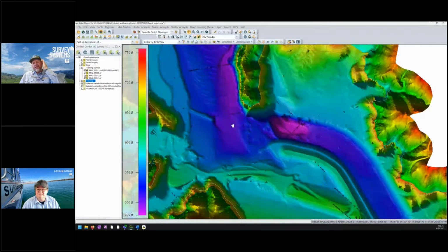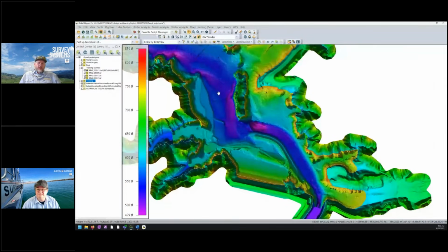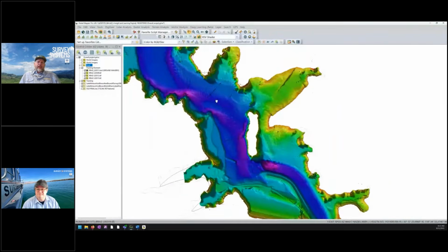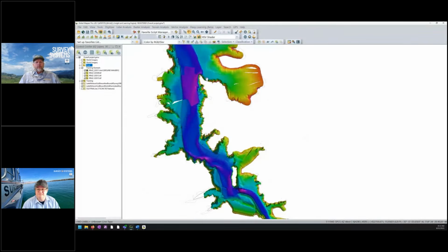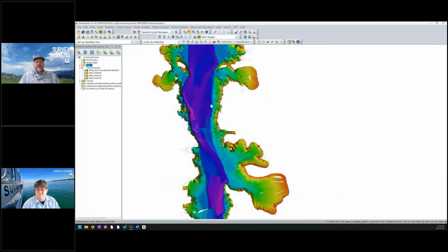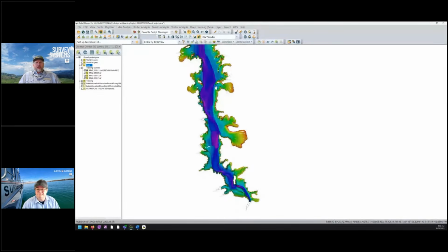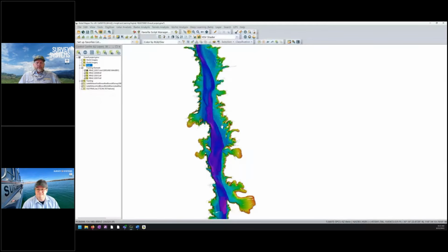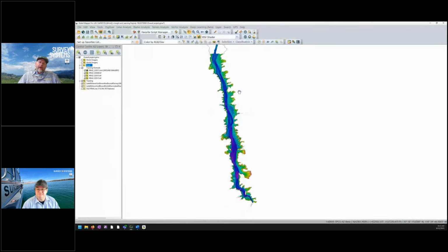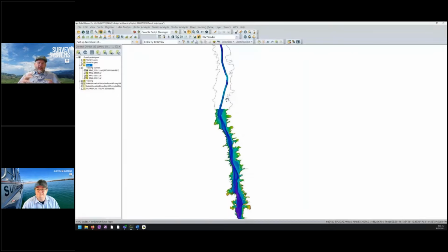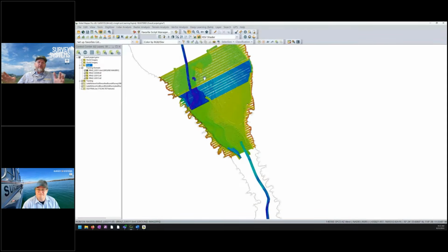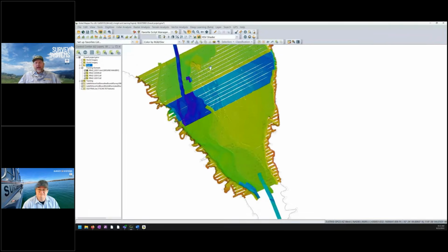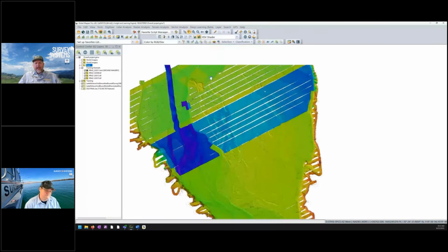The huge benefit on the data collection side is that area that Joe was showing you is where the ancient bed of the Colorado River used to run. It's still running there. When we got into that area, we identified it because of the sound velocity change at the sonar sensor, and the water above it was coming up. So we got our hands full on the data collection side, but if we know what our coverage was and we know where we're safe, we're able to communicate back and forth from the office to the field to make sure that we're getting adequate coverage.